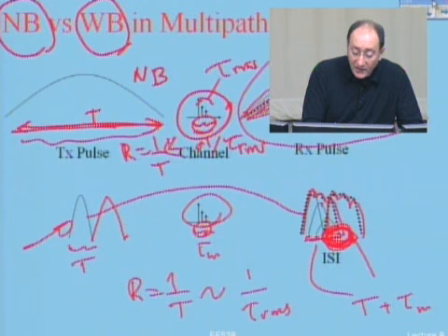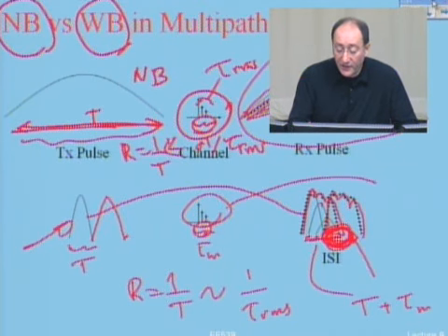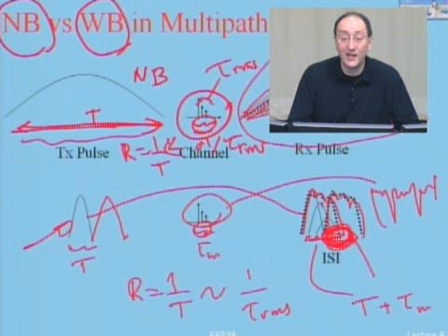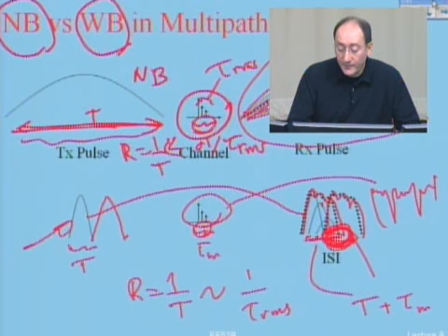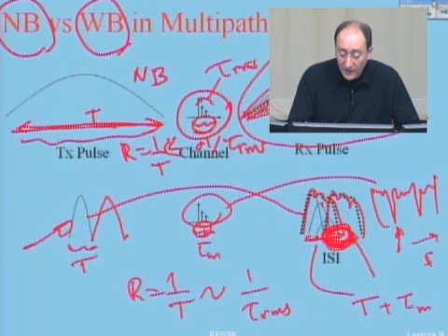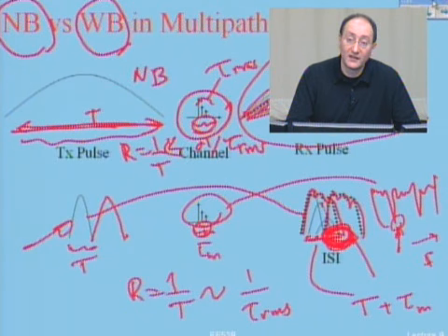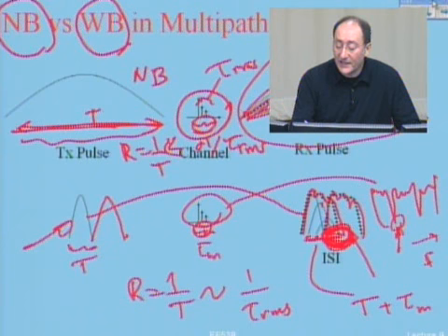And this multipath, if I go to the frequency domain, is what? If I take the Fourier transform, it is something like that. You remember that? And this axis is in frequency, not in time. These were called what? Frequency selective fading. So in reality, if I am in a narrowband signal, I'm operating either in here or in here.